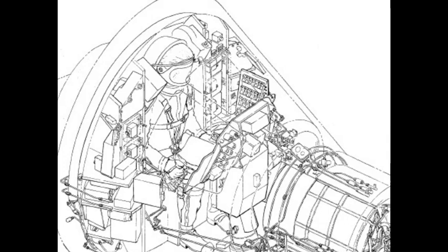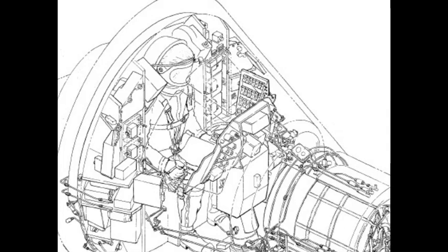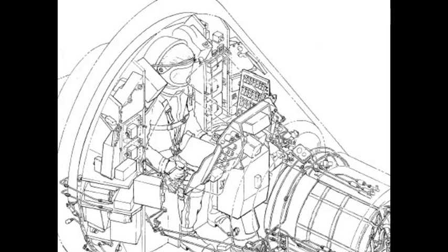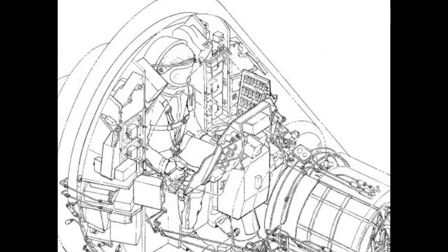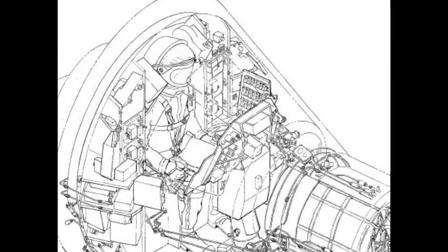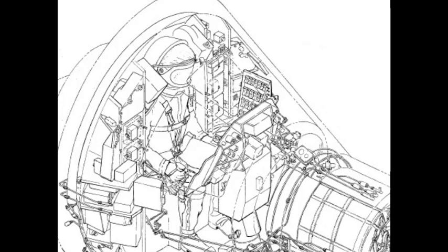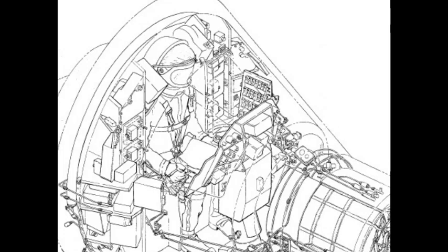The outer window assembly consists of a glass pane sealed in a titanium frame that is attached to the capsule outer skin. The outer window assembly is sealed separately from the inner window assembly to provide a complete seal. The outer window conforms to the curvature of the capsule conical section. The observation window is equipped with shades and filters, enabling the astronaut to regulate external light entering the cabin.